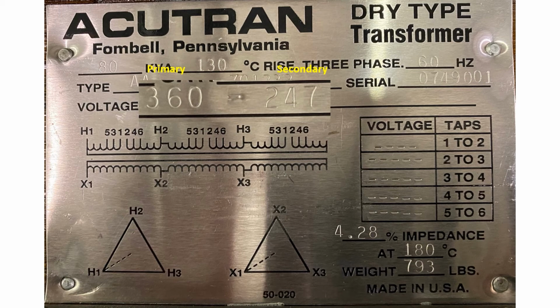You'll also see that the common windings that we're going to be looking at, the A phase winding for the primary will be H1 to H3, and X1 to X3 on the secondary winding. That's the comparison that we'll make. And the same thing for the other two phases. Finally, because we know that we have a very straightforward calculation here, we can just simply take the primary voltage, divide it by the secondary voltage, and we can calculate the ratio of this transformer.